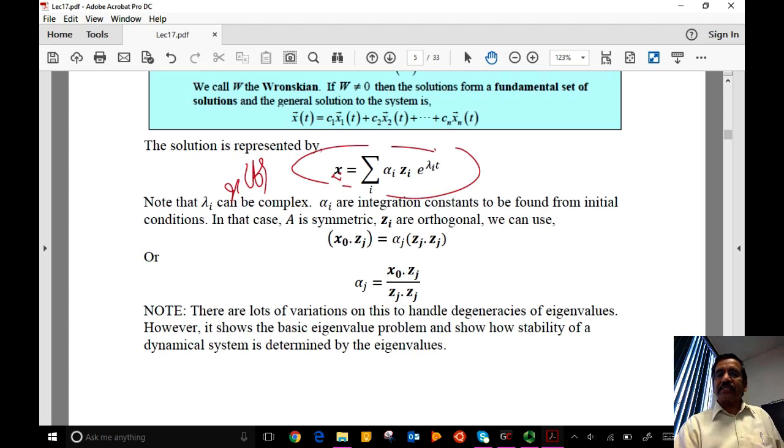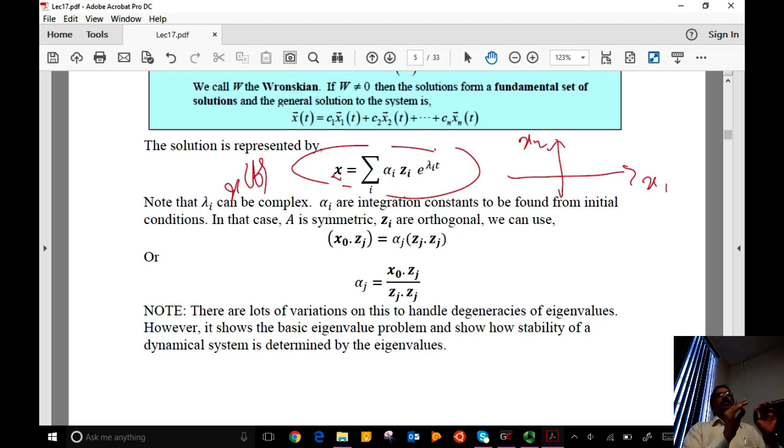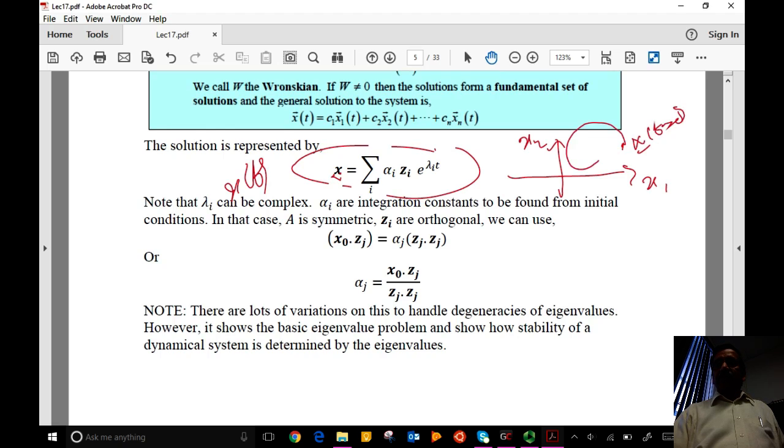Right? So what does a state space mean? It simply means if I have a two by two system, x1 and x2 are called the states of the particular system that I'm modeling. For a CSTR problem that you did, for example, temperature and concentration are the two states. So I can plot temperature on one axis and concentration on the other axis, and if I give some initial condition of x at t equal to 0, this trajectory will go something like this and maybe reach a steady state.